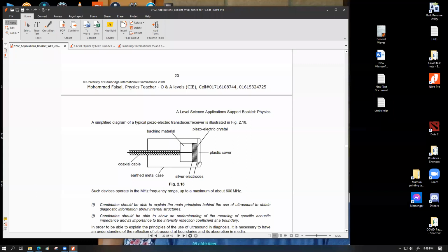The ultrasound can flow forward. And if it is used as a medical probing device to detect things within the body, these ultrasounds can go into the patient's body, get reflected from different sharpness of objects, and eventually be reflected back. Whenever these ultrasounds are reflected from different layers inside the human body, the final layer happens to be the backbone. Then this piezoelectric transducer would now be affected by the reflection of the ultrasounds, which it itself created. So it will produce sound, then wait for the reflections.